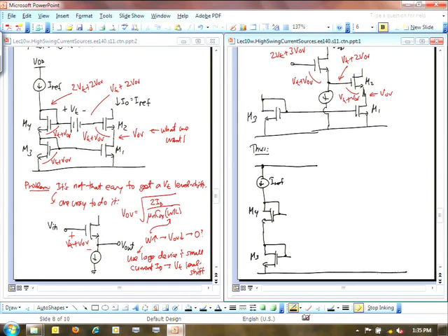And I'm going to have that level shifting thing pulling straight up to VDD from the drain, pulling down into another device that's really serving as a current source now for it. So I've sort of implemented this little current source that I've drawn right there using an MOS transistor. Call this M5, call this M6.